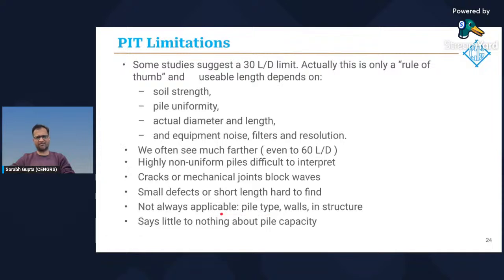And it's not always applicable. So, if the piles are below an existing structure, you can't access the pile top. Or in some cases, of walls and D walls, you can't really use pile integrity tests. It's not meant for that. Last but not the least, because a lot of people ask me this, PIT says little to nothing about the pile capacity. The intention of the test is to figure out the structural integrity of the pile. If we want to understand how the pile is going to perform geotechnically, or what kind of loads we can apply on the pile, then definitely you need to go with the statnamic or dynamic pile load test.